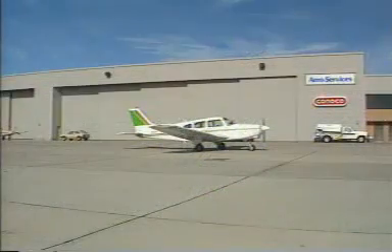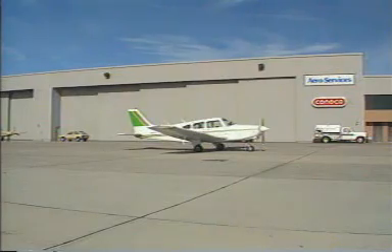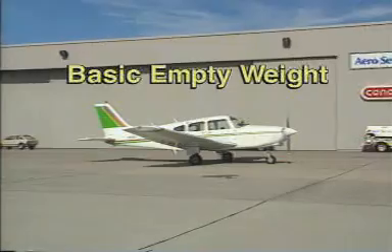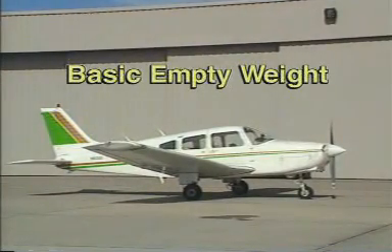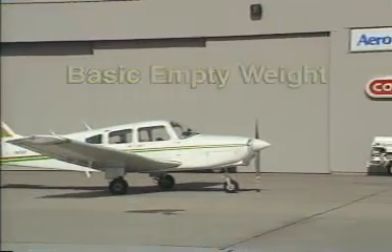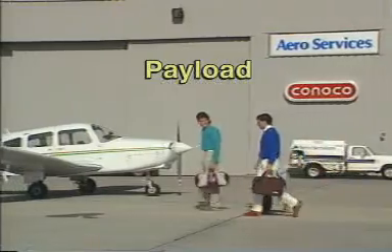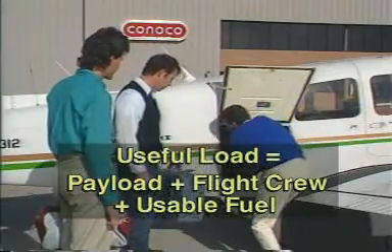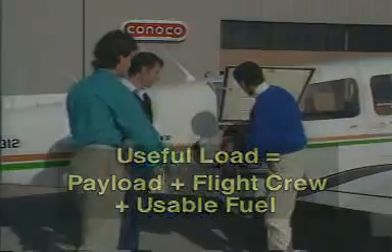Let's begin our discussion by looking at the various aircraft weights with which you should be familiar. The starting point for any calculation is the basic empty weight, which includes the airplane, optional equipment, unusable fuel, and full operating fluids, including oil. Payload includes the weight of the passengers and any cargo or baggage. Useful load includes the payload and the weight of the flight crew and usable fuel.